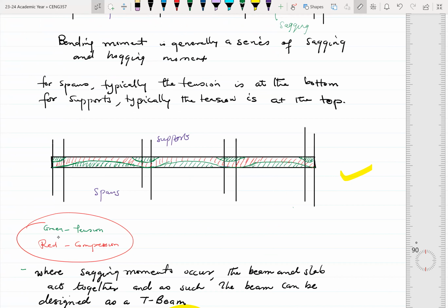Normally, when it comes to reinforcement for bending, we have two types. Either we have the singly reinforced, where you are only required to reinforce the tension zone where tension failure is likely to occur, or you look at the case where you need double reinforcement, because concrete is likely to fail in compression, or the concrete compression is not enough to resist the loads coming onto the structure. So we have these two loading arrangements.